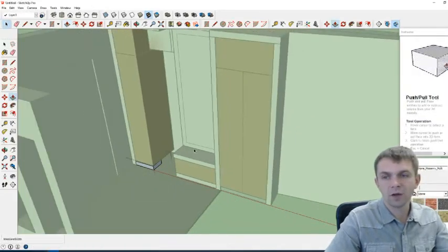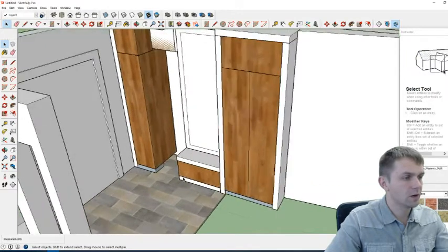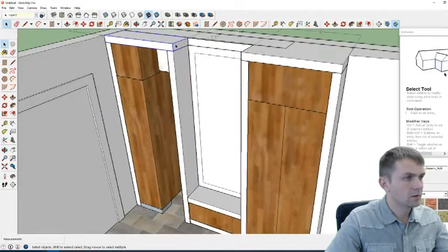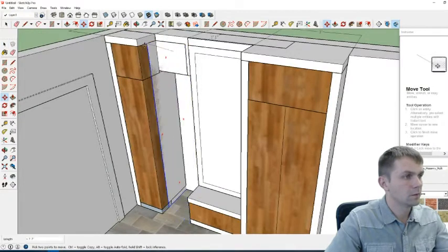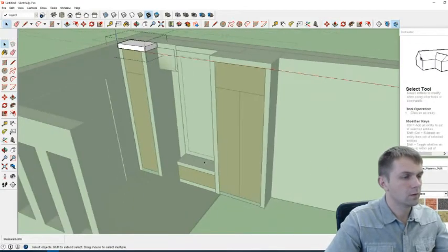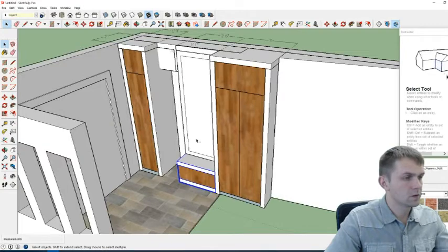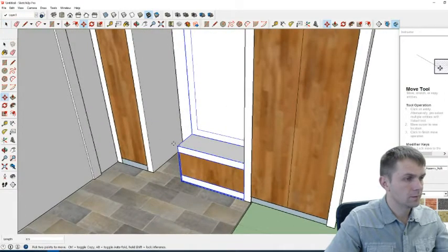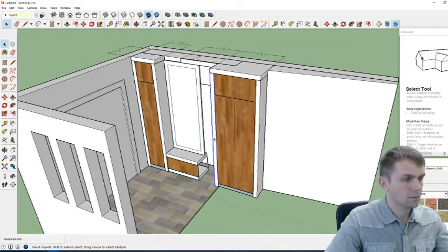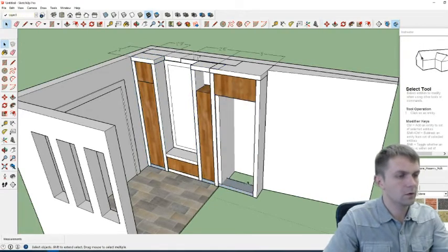So see how when you have blocks, how easy it is to modify and create a different option. And now we go edit, unhide all, P for pull, P. So now we have that. The whole middle section we just move. And then we copy this section into here. Get rid of this whole thing.